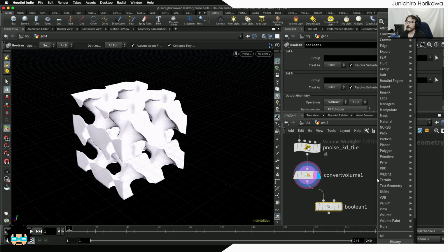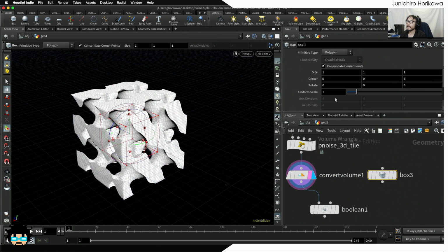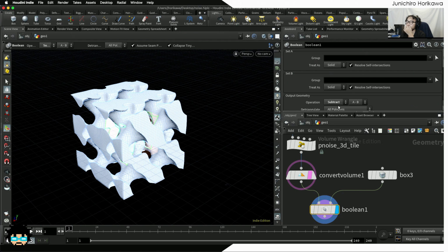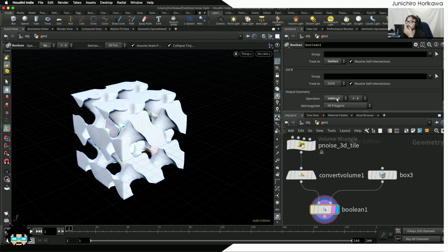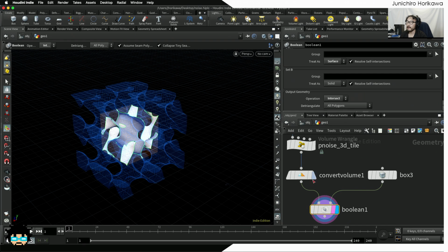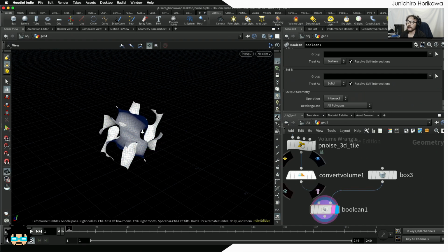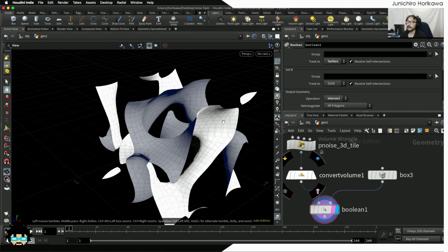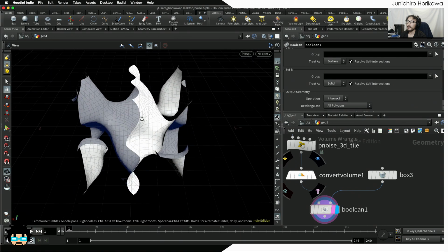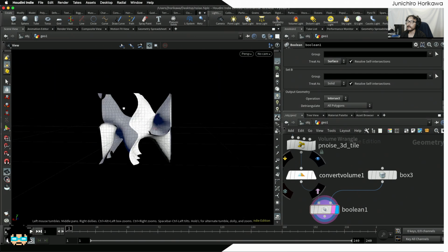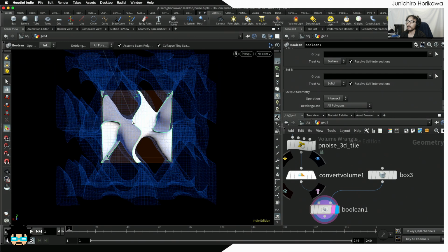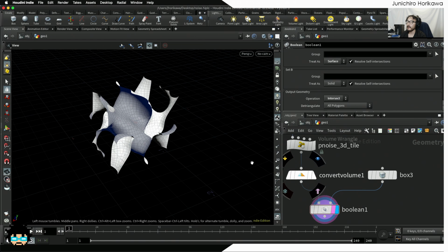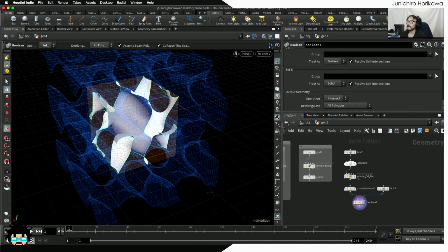and together with the box which has the size equal to 1 by 1 by 1, and use the operation something like intersection between the surface and the solid with the intersect. And as a result, you'll be able to get this intersected surface like this. And this is actually a repeatable surface for the top part or left part on the front part. So let's try to check that out.